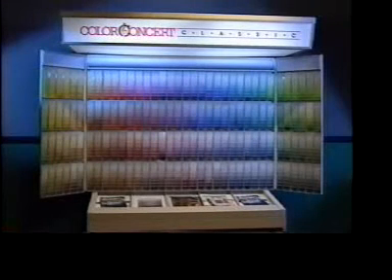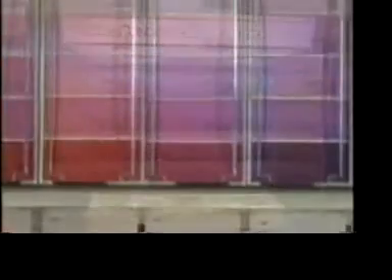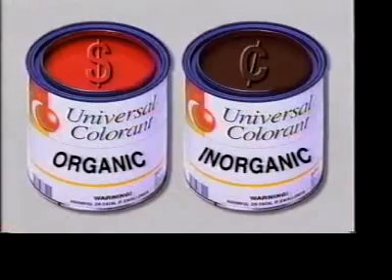Organic and inorganic colorants are used separately or in combination to create every color called for in a typical in-store color display system. When mixing custom colors, there are two factors to consider. First, there are several important differences between organic and inorganic pigments. Second, there is your choice of colorants to combine to create the correct color. It is important to consider the cost factor of inorganic and organic pigments when formulating colors. For cost-efficient color mixing, maximize the use of less expensive inorganic colorants and minimize the higher-cost organics.